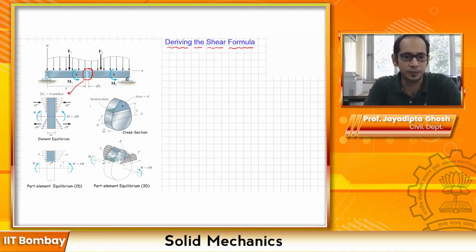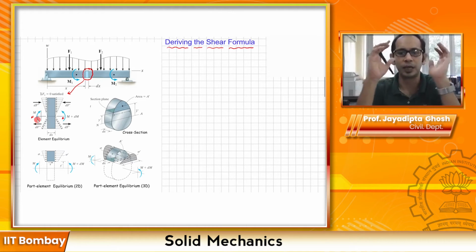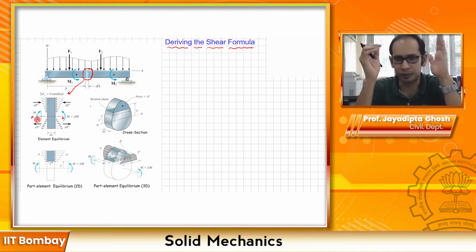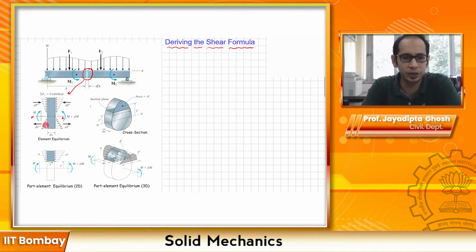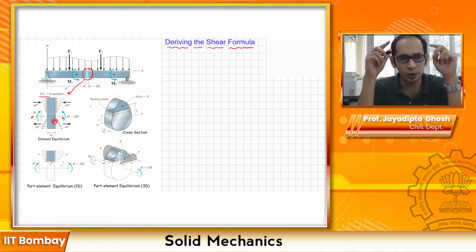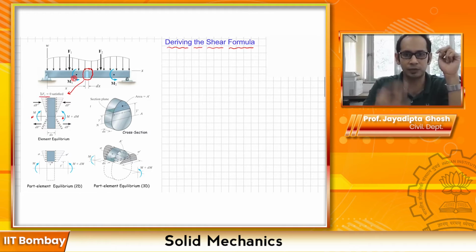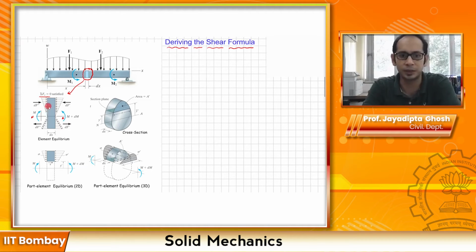So this cross section over here is subjected to a variety of forces. This is your neutral axis, and this cross section undergoes bending. Remember when we took that small beam element, we had M on one side, M plus dM on the other side, V on one side, V plus dV on the other side. You don't see the V over here because, when we write the equilibrium equations, we are primarily considering summation Fx equals 0. The V and the small w, that is the UDL, act vertically down, so that is ignored in this case because we are primarily interested in the x-direction forces.